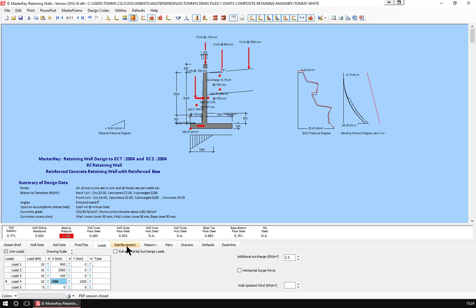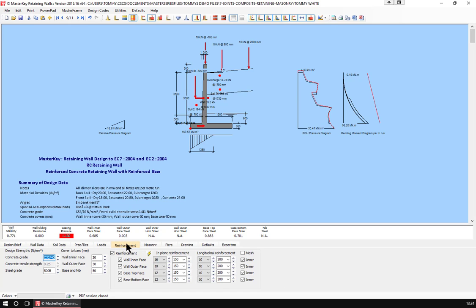So what I'm now going to do is go into reinforcement, and as you saw, we can have the C32/40 concrete. We're going to go for 500B. We have all the different grades, and you can add in your own grades if you're working in Africa. I know quite frequently in Africa they're still using in some areas 425 rebar and the Y designator, whereas we're happier working with the 500B in our reinforcement.